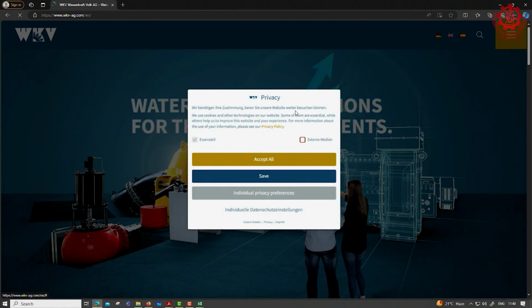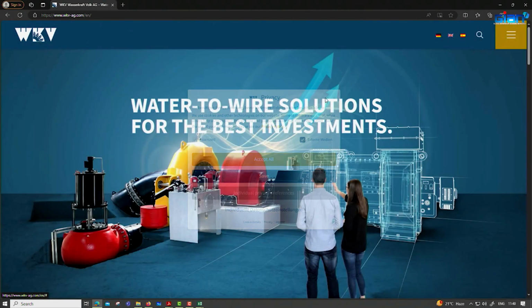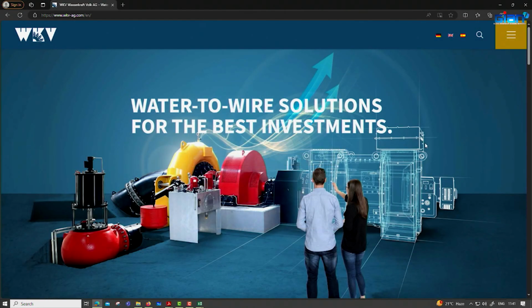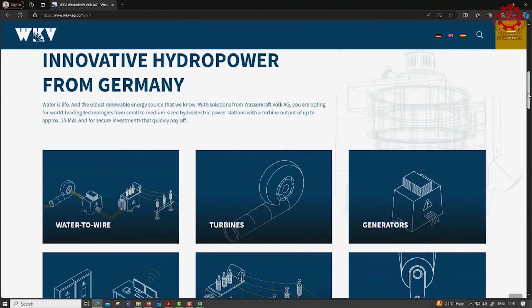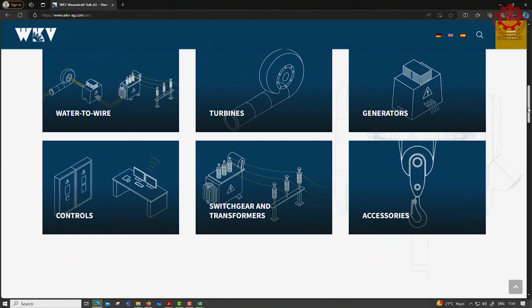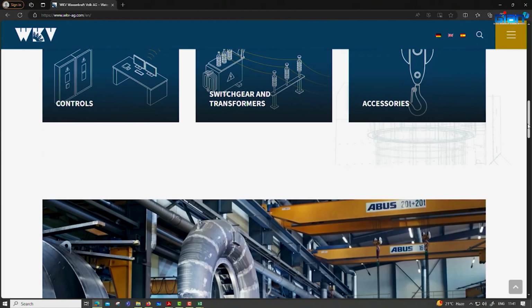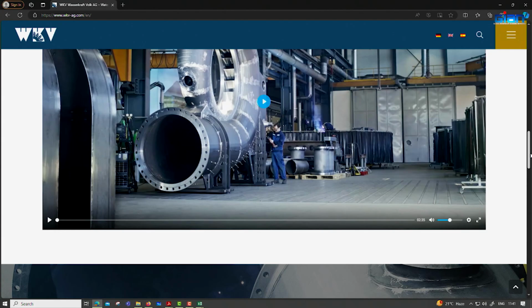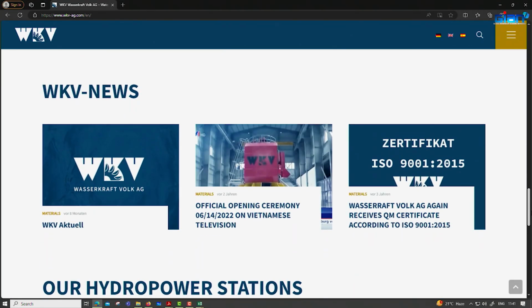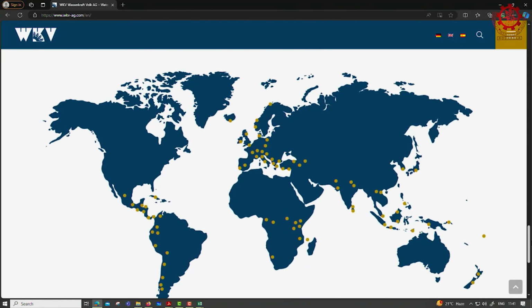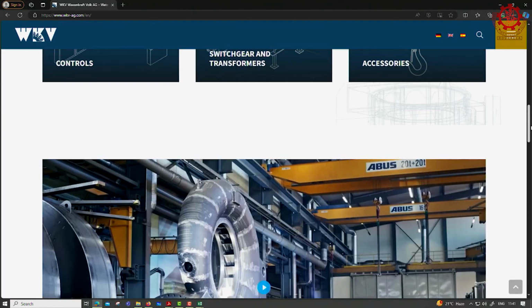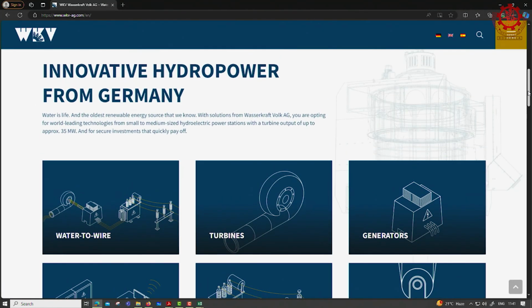We once bought equipment from this supplier. He is a good supplier. He will have a lot of information in his various sheets. There are many such equipment manufacturers you can refer to. You can search for small hydropower turbine manufacturers, and among other things they will have somewhere in their documentation turbine selection charts. I do not know exactly what is the place.